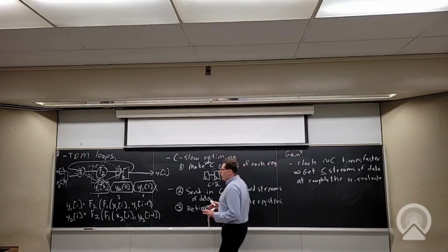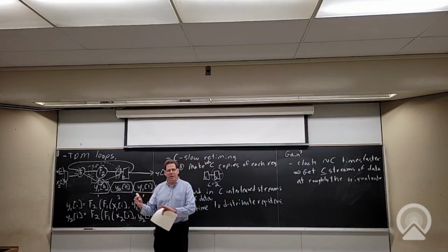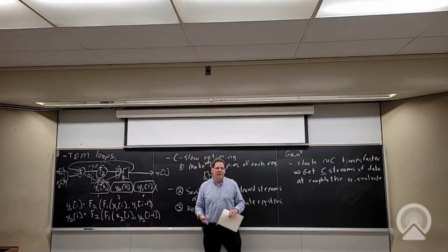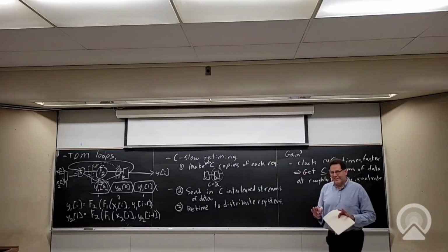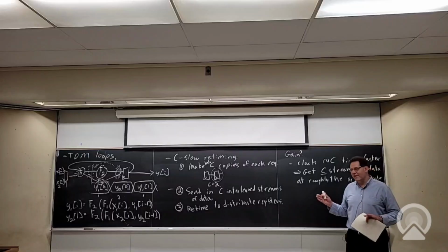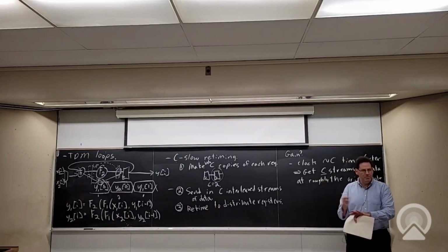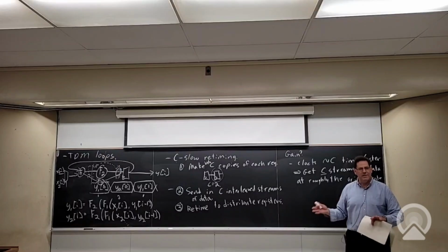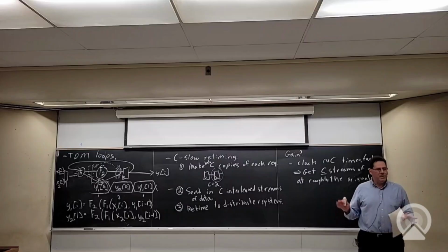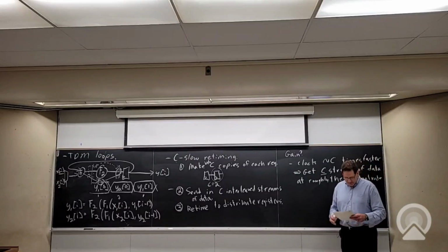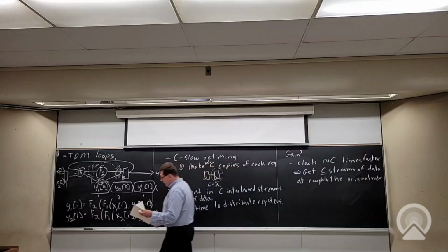And the most coarse one, if you've got the big picture of your pipeline and you try to put things in roughly the right spot, it still doesn't have as much insight as a human does, right? It applies sort of local heuristics, which hopefully will get it to a good spot in those early synthesis optimizations. But not always, right? Because it doesn't necessarily see, I've got all these registers, they're not balanced, I should move them all at once. It tends to try to move them one at a time, and hence it may not see the gain. It can get stuck in local minima. CAD engineers try not to do that, right? So it may not get stuck, but it might. Does that make sense? Any other questions on this?